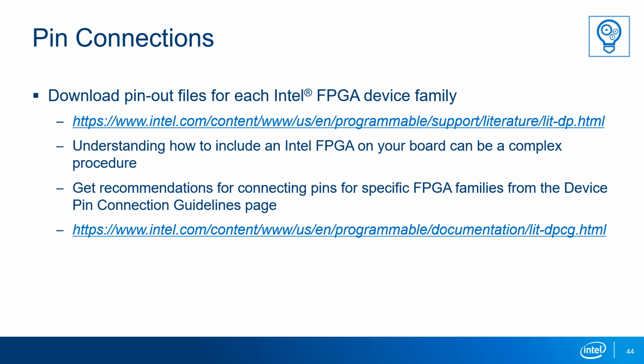Verifying pin connections prior to committing to hardware is a critical step that will help reduce the chance of needing a board respin. The pin connection guideline documents, also linked here, should be read and followed when you develop your pinout and when you review your pinouts prior to the final layout of your board. And then lastly, we always recommend that you generate an example design with all the IOs and the clocks defined in Quartus. Using the latest version of Quartus will help check to make sure that there are no pin violations to help ensure the success of your Agilex design.